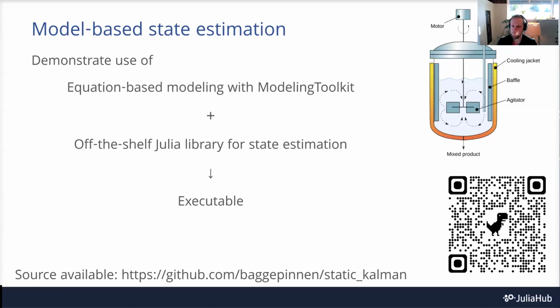Two different reactants are reacting and combining into some desired outcome. That produces heat, and to mitigate the heat production, we have a cooling jacket around the tank reactor that can cool. When the reaction takes place it generates heat, and that makes the reaction go faster. So that's an unstable system, an interesting system from a control perspective.